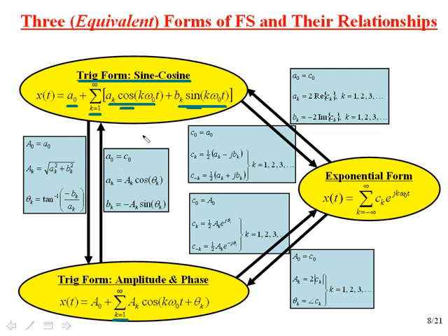And what we can do is specify how to calculate these Fourier series coefficients. We've got the A sub k's and we've got the B sub k's. So we can get there from our exponential form by, again, A sub 0 is equal to C sub 0. The A sub k's are just 2 times the real part of C sub k for only the positive k's. B sub k is just minus 2 times the imaginary part of C sub k.